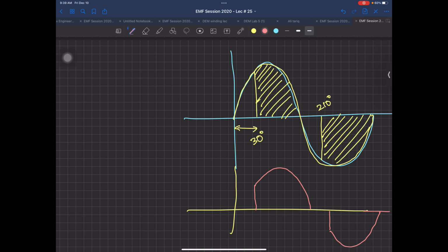So it's not a pure sine wave. It is a discontinuous sine wave, where you have taken this portion out of your circuit. And this is the reason why, because when you reduce your dimmer, a point comes, supposing, let me mark that over here, you have set the angle to 150 degrees, this shaded portion, the pink color.